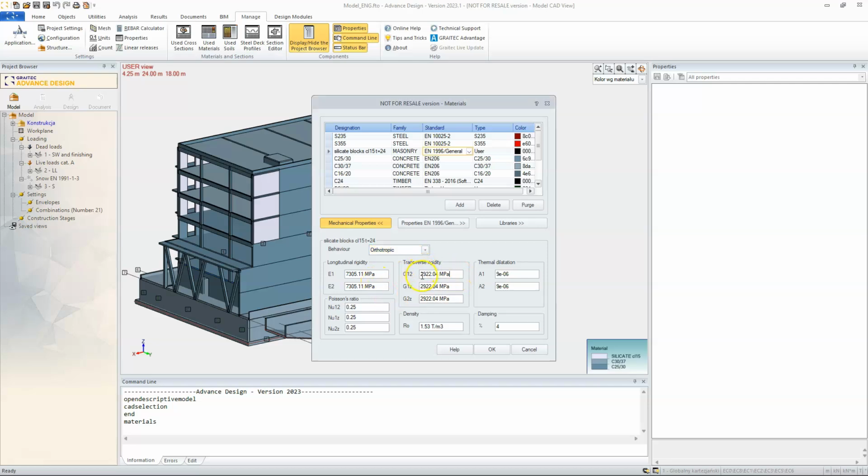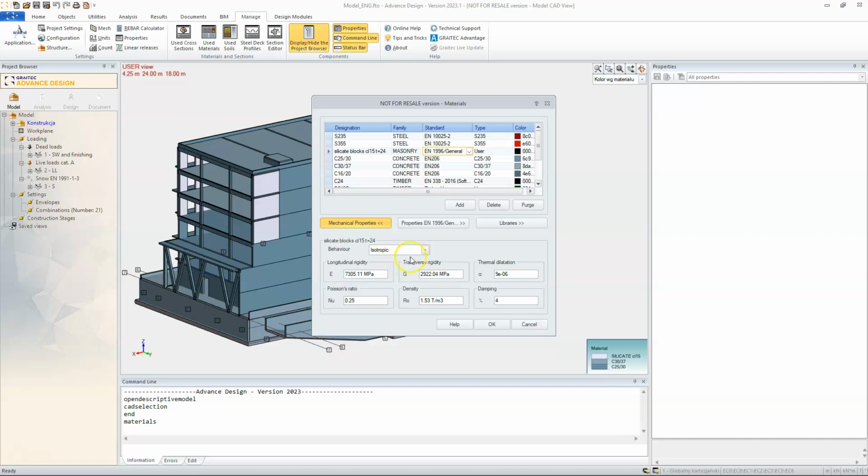In most cases for masonry walls, we could introduce some reduction to the scale of rigidity for this G in the 1 direction, usually about 80 to 90% of reduction. But this time I will just leave it as isotropic, so it has the same values in both main directions, according to the x and y local axes.